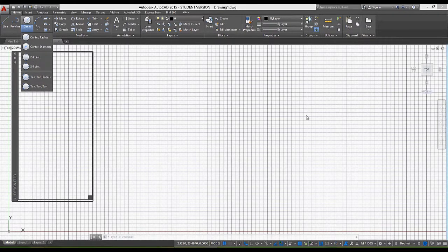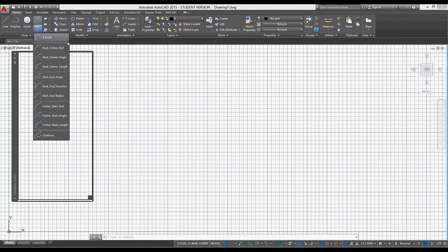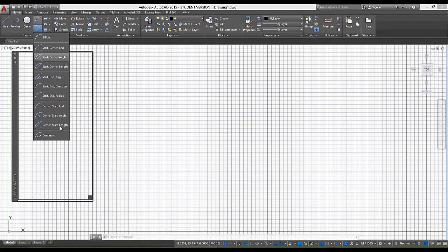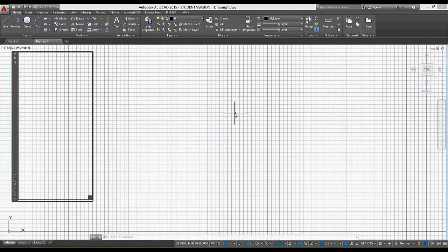So in addition to just creating a circle, there are different ways of creating a circle, and AutoCAD has taken that into account, and it gives you those extra options. You'll find that with specific tools, they will have that arrow indicating that, for example, under trim and extend, this is actually a different command other than trim, which is on top. But if you have, for example, the arc, these are different ways that you can actually create that arc. So it has the two with it, and it allows you different ways of getting the result that you want.